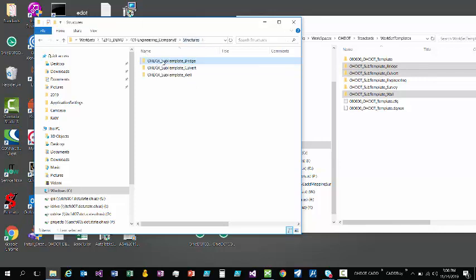So the name for a bridge should be SFN underbar and then the 7-digit number for that. 1, 2, 3, 4, 5, 6, 7. And if the bridge is being replaced, this number should be the new SFN, not the old one. Now walls should just be wall and then a 3-digit number. And then culverts should be a CFN and then the 7-digit number. And same thing with culvert. If the culvert is being replaced, this number should be the new number. The new, not the old one.